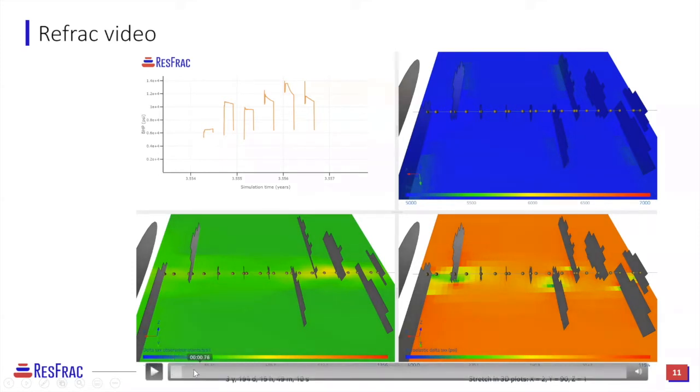And there are a couple observations to make. Here's when we start pumping in for the refrac. The yellow dot in the upper left indicates where we are on the scale. What I plotted was bottom hole pressure versus time. So we have 6 refrac stages. It's exactly cut in half.